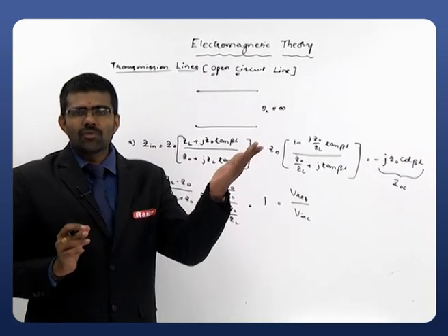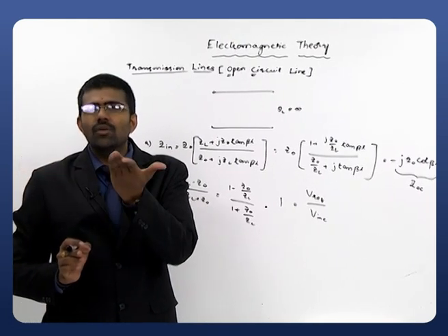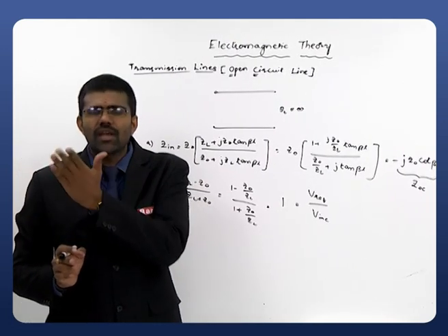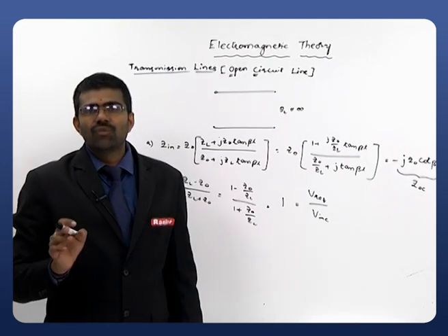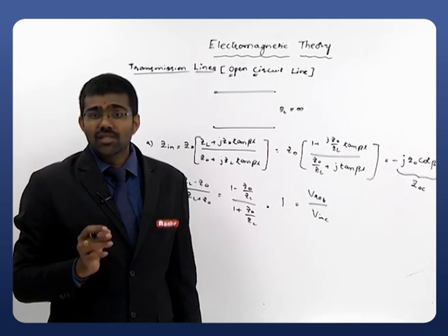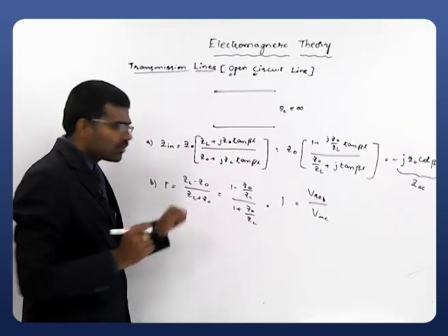So whatever signal we apply to a transmission line, it's not going to the next section again. It's not going to the antenna. It is not going to the free space. It stops there and reflects without any phase shift. So once again you can observe the voltage standing wave, and the maximum voltage standing wave ratio will be there. That we will observe now.